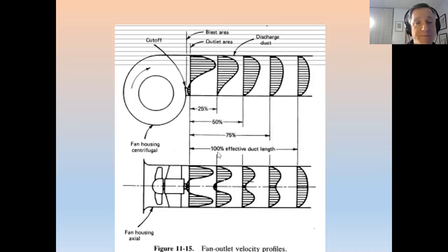So this is important. It's important that designers understand this, so they don't put, let's say, a discharge right here, the discharge of the fan, like you're designing something, cooling air or whatever it is, or something to run your Legos machine with a low pressure pneumatic system or whatever. And if you put it in certain places, you won't get positive air. You could make things worse. So all you're going to do is burn electricity and not produce results that you want.